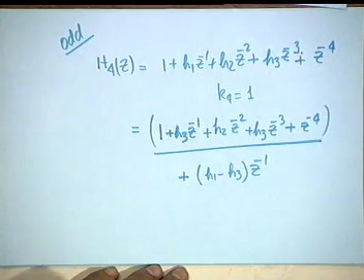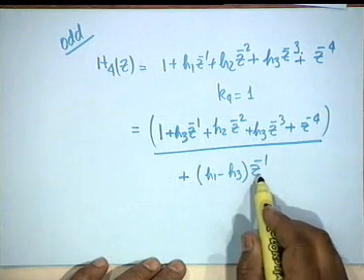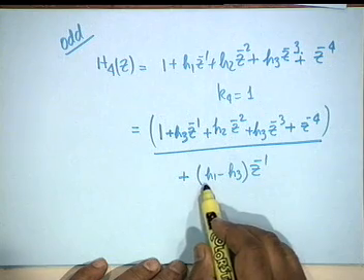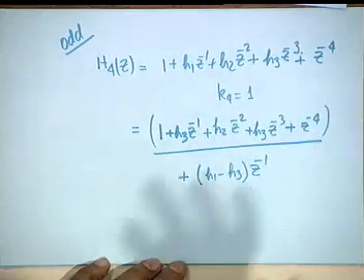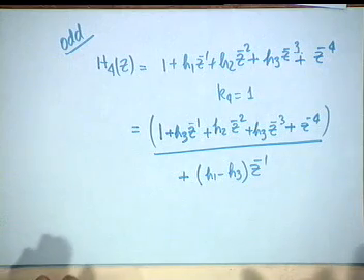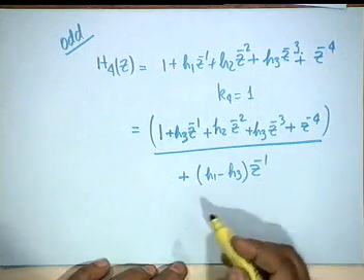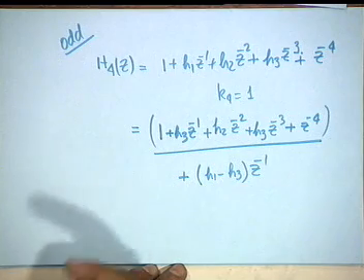Now in that realization, that is not enough, you have to make a parallel branch now, in which this transfer function is h1 minus h3 z inverse. This is also linear phase. Okay? Z inverse is a linear phase, it is a trivial FIR linear phase. But where would you pick up after the first delay?